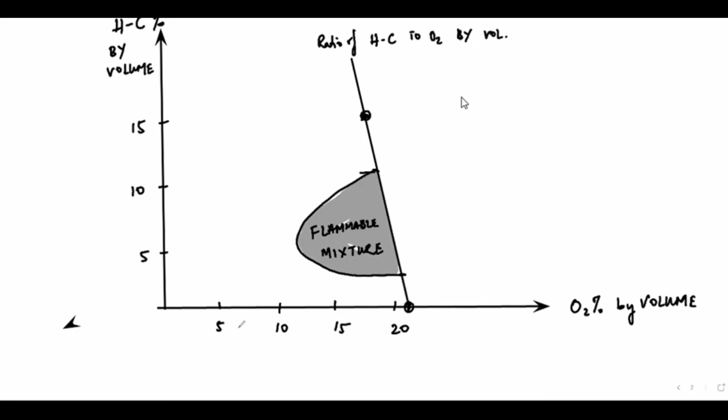And for this reason, we are not going more than 8% in the tank. So if I have an inerted tank, I will always maintain at 8%. It means no combination should fall in between, no flammable mixture. Yes, this is my inerted tank.